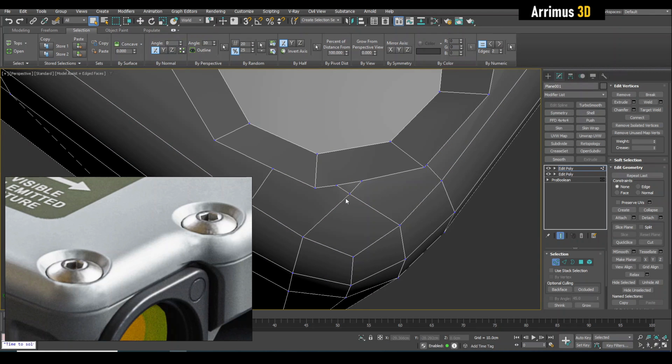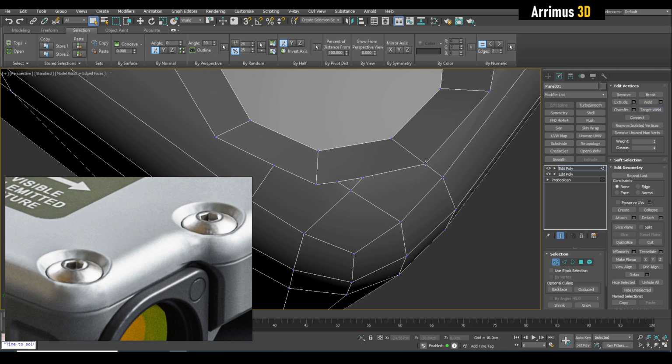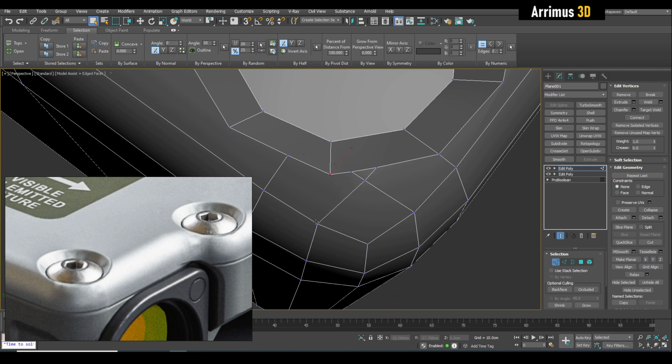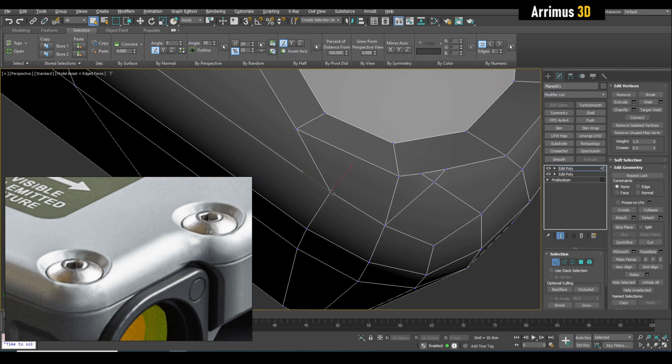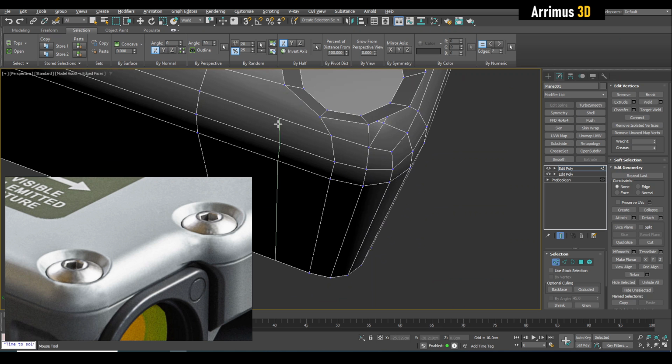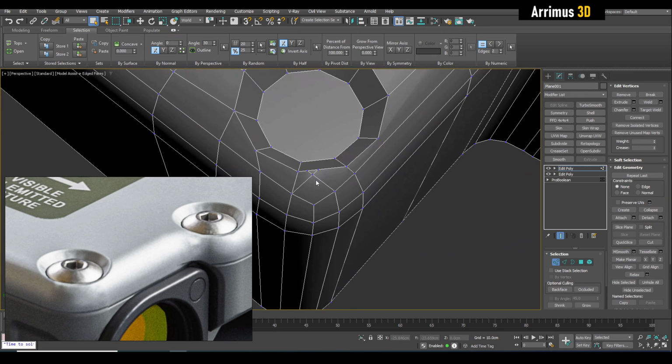So to solve these kinds of issues, now once you get good at topology, you kind of figure out what's the best way to do this. So I would just do something like this, for example. Limit edge constraints. Insert loops where necessary. As you can see, just keeping things as simple as we can here.